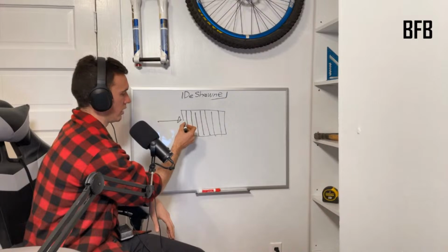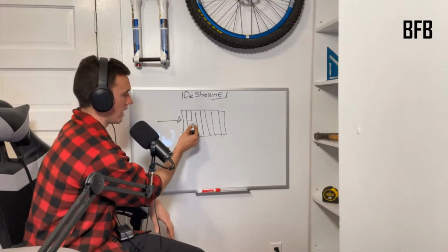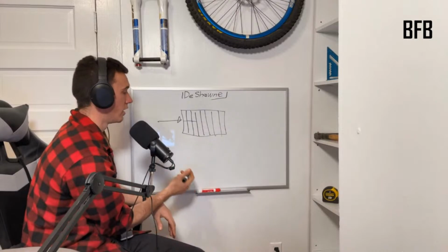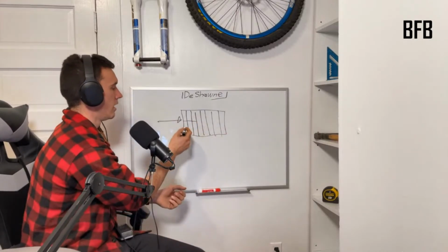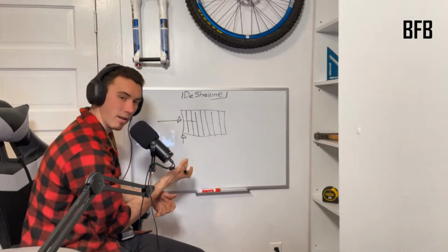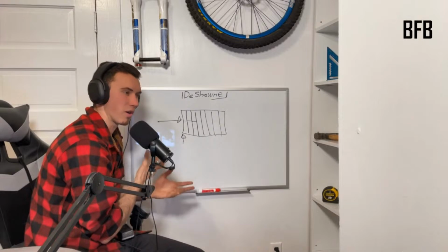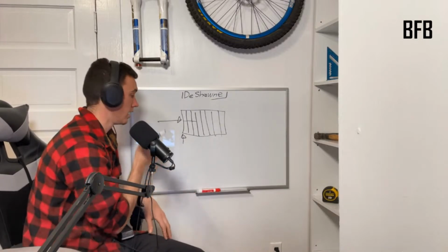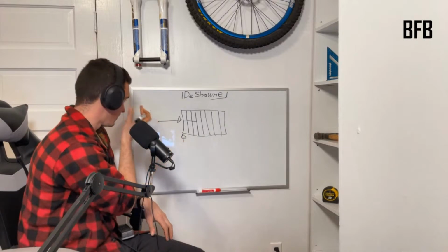Well, you could insert a block there, and then maybe you can add one there, and you can add one there. You could go all the way down the roof or all the way down the ceiling, just depends. Now, each time you add one, the first one is going to get stronger and less likely to move, and it's going to be able to handle it without breaking or bending, really. Because a lot of times we don't want sheetrock to crack, so we don't want things to move at all, really. But that's the premise.